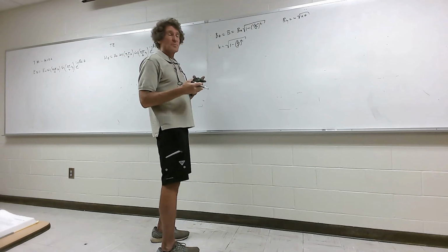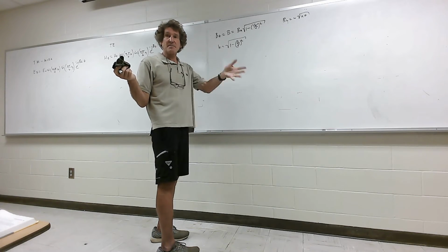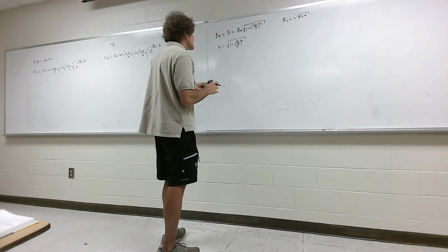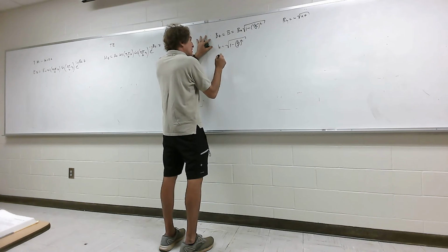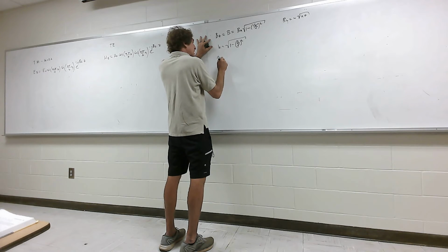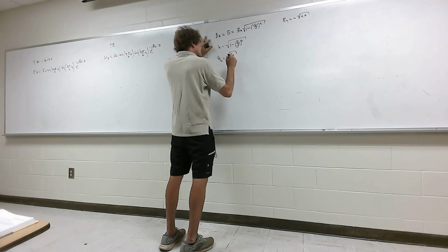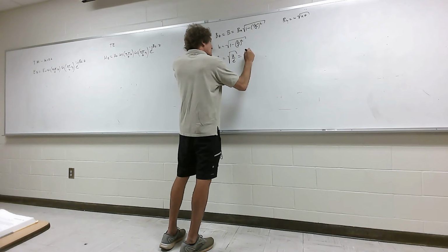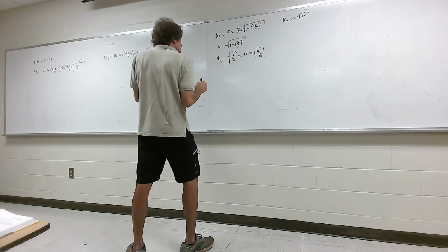And in the problems I gave you, they said calculate the first 9 lowest order modes. So you've done that. Next, we talk about the actual waveguide's internal impedance, and you can call it unguided, but it doesn't really matter. That's the square root of mu over epsilon inside the guide, which is 120 pi times the square root of mu relative over epsilon relative.